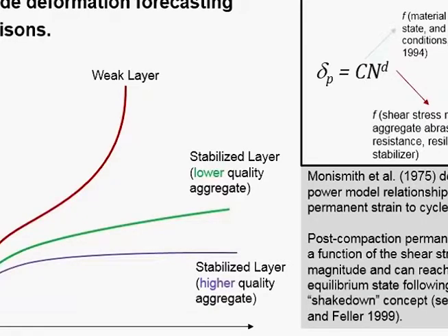Now, when that sinks in the ground, the permanent deformation tends to follow this red curve. We reach a bearing capacity failure. That's not a good situation. The green's kind of intermediate, and the purple's kind of where we want to be. We want to be able to push on things and not accumulate permanent deformation.